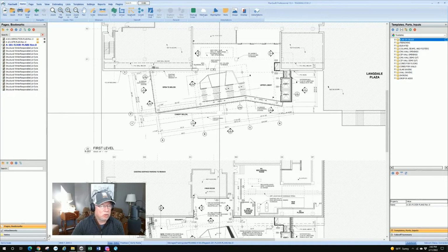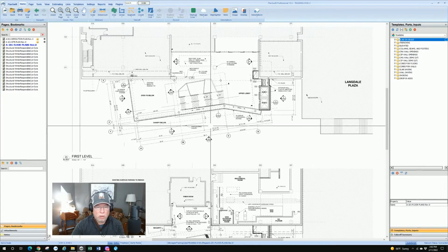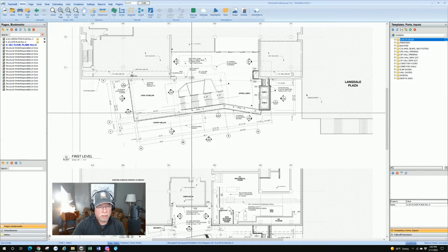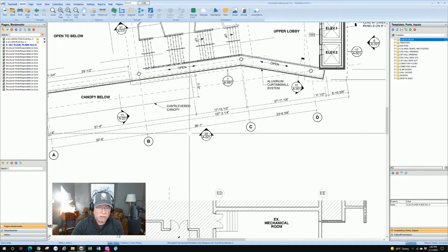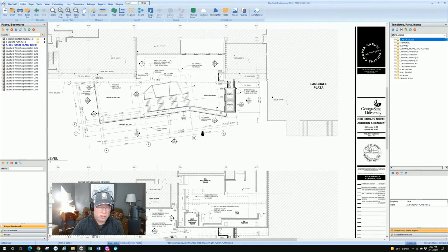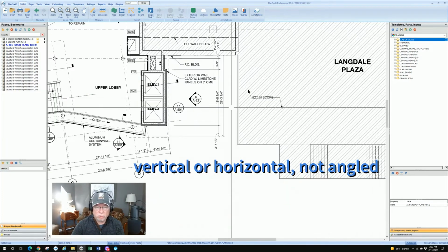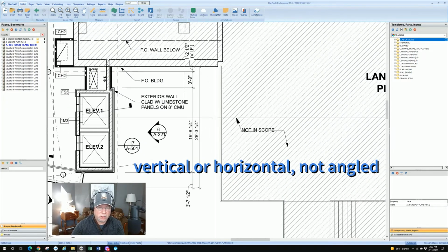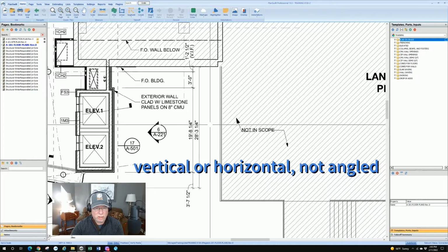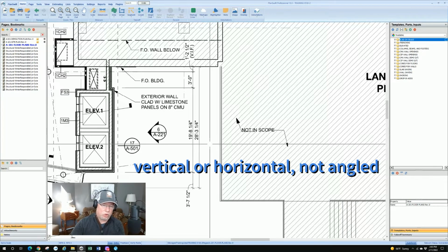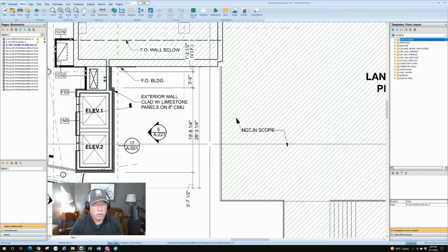So we've got a drawing here in this floor plans with a lot of dimensions. It makes it real easy to create the scale and apply it. So we see these dimensions in here. I'm going to go with one that's either 90 degrees or 180 degrees just because it's a little easier to deal with for the purposes of this video. Here's a nice dimension. When I say 180 degrees top to bottom, it says 28 feet 3 1/4 inches.